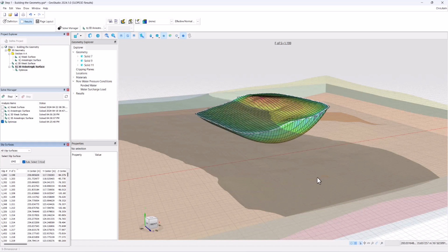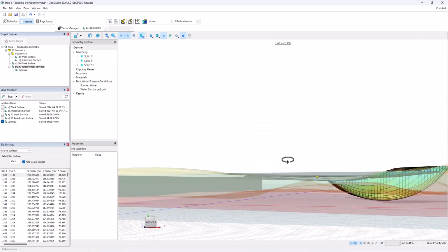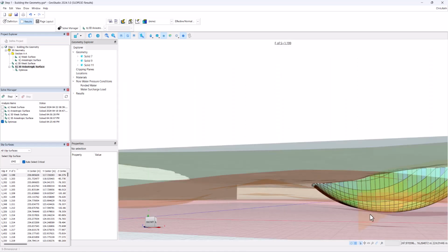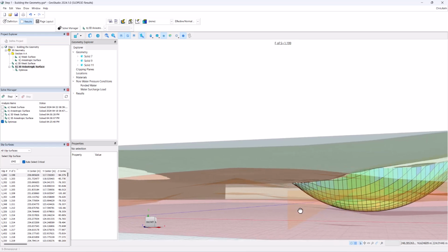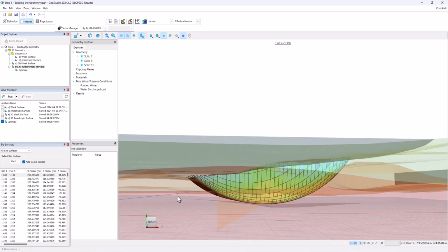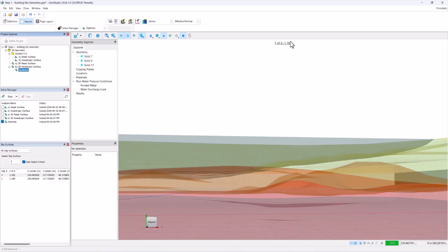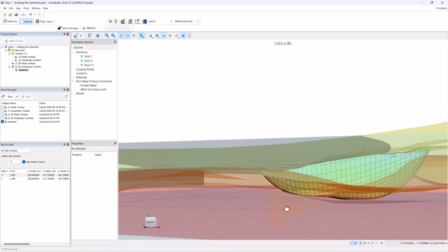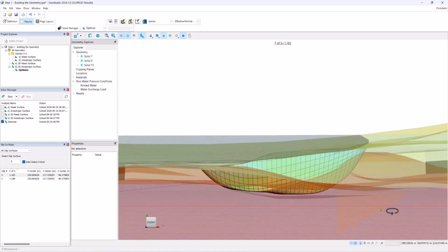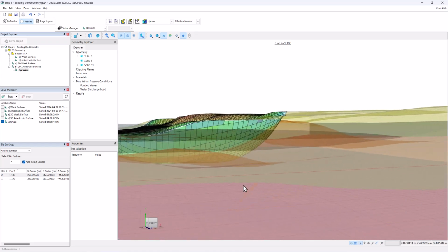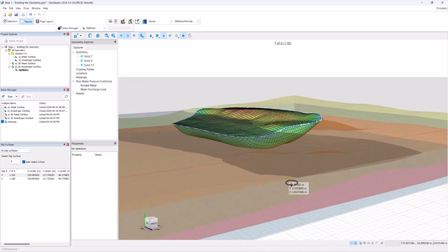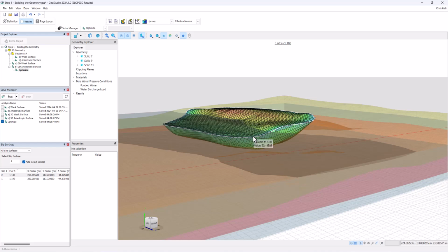We see 1.2, and the base of the sliding surface is just slightly above that contact between the disturbed shale and the intact shale. Then when we go to optimize this surface, we see the factor of safety drop somewhat marginally, but the slip surface shape now adopts a more translational retrogressive mode of failure. In short, then, both the 2D and 3D analysis capture the key mode of failure for this type of problem.